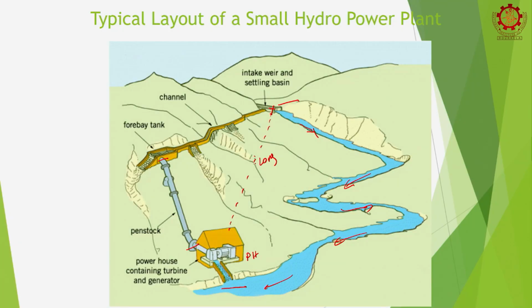And on the other hand, when the water flows through the penstock, depending upon the penstock diameter and the internal resistance, there will be internal losses. We call them head losses in technical terms. Therefore, longer penstocks have longer head losses. Therefore, the electricity amount you can generate from a long penstock will be comparatively lower than from a short penstock. Therefore, we want to bring water to a convenient location on a canal, and then start the penstock from there to keep the penstock as short as possible, right.